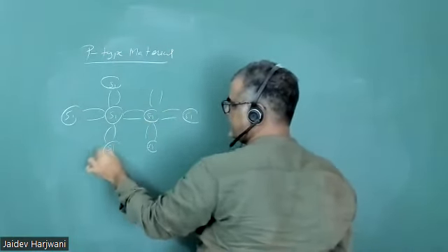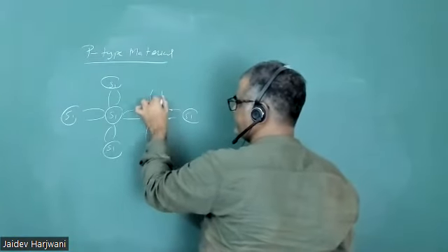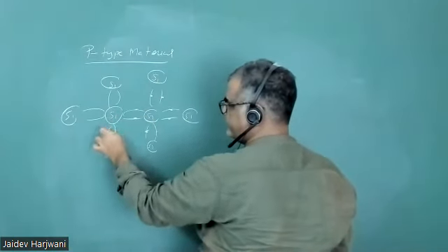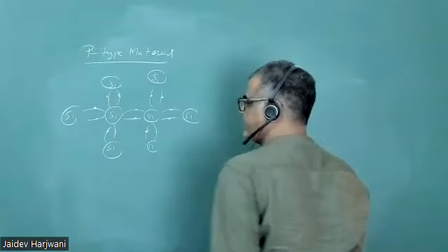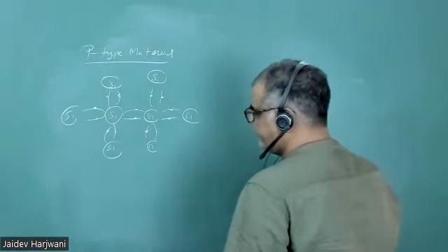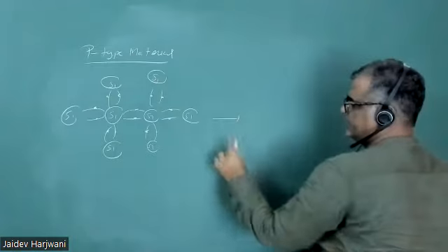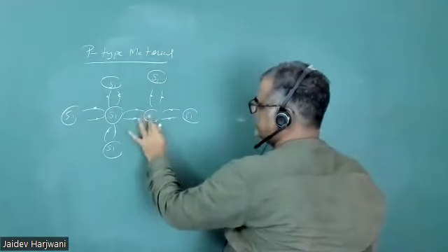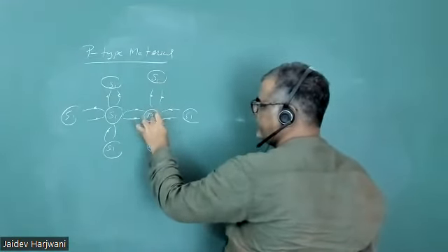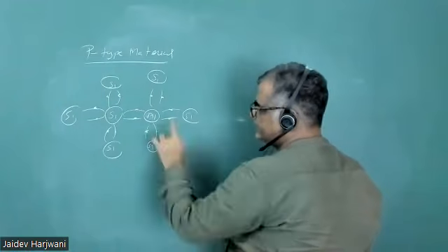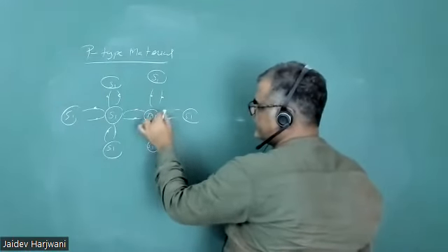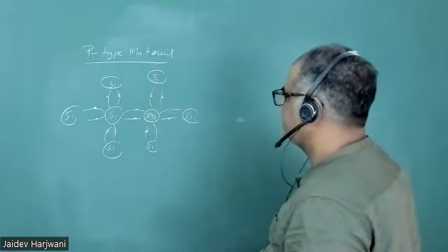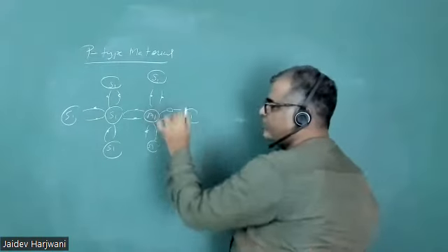So silicon again has 4 electrons. Now if I do doping, here itself I'm doing doping. If I replace this by aluminium, aluminium has only 3 valence electrons, so it can share 3 electrons. So it has 1 electron less compared to silicon. So here we have one hole present.